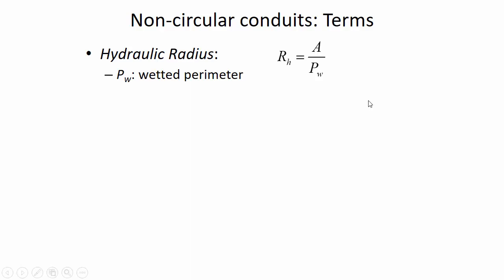You will recall hydraulic radius for a pipe that's flowing full is the diameter divided by 4. We can't make that same simplification if it's a non-circular pipe. And so the hydraulic radius we would actually calculate, instead of just having D divided by 4, for whatever the shape cross-section, we'd find what is the area of that section and what's the wetted perimeter of that section.